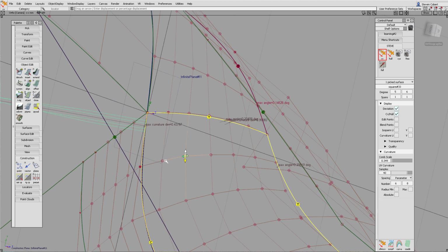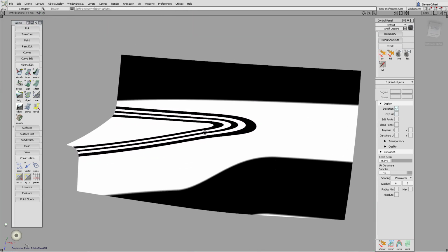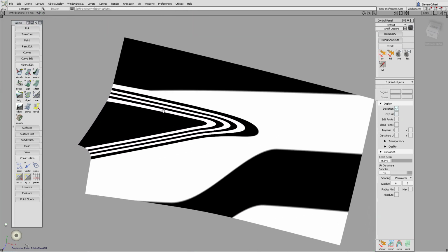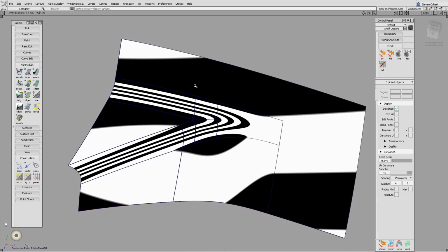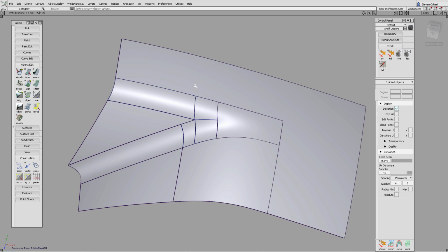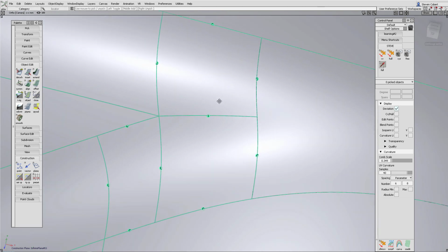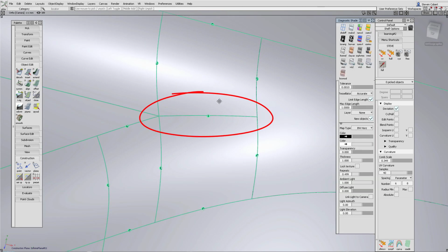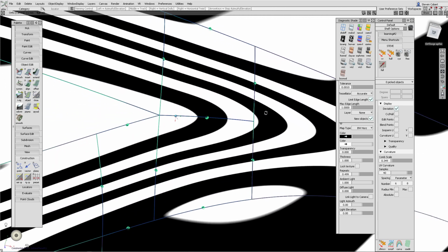The quality of the final highlights will depend very much on how accurate the large corner surface was, and you might find that you have to revisit the original surface a few times to get the very best results. The common edge we may not achieve G2 on in all cases, but as long as the highlights look okay, then this is usually not a problem. We can also assess this by looking at the curvature across this edge.